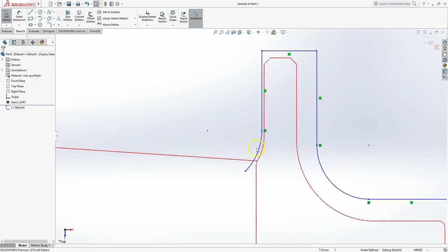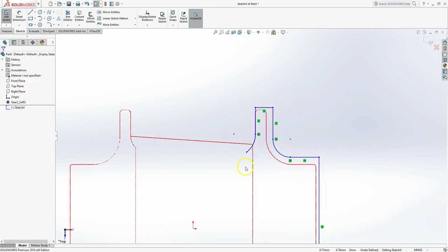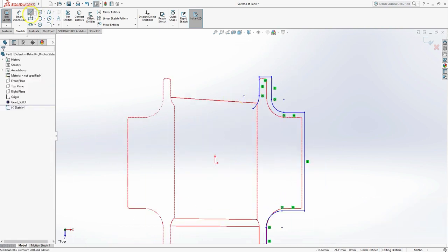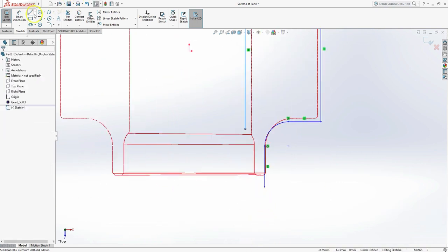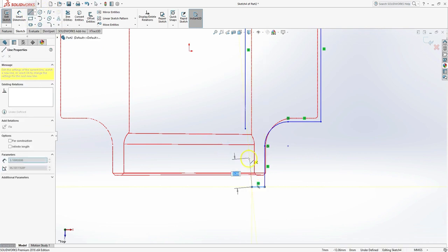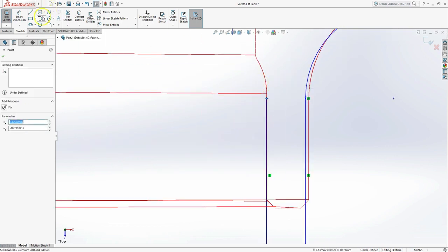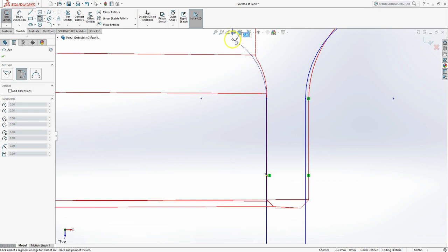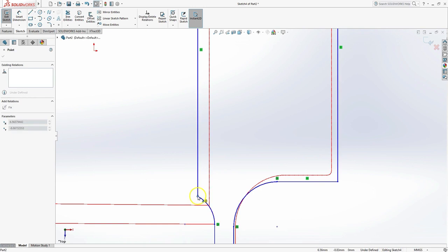Now, I'm going to do something a little unique. On the inside here, I'm actually going to make sure I have extra material because we're going to be cutting that out later. So right here, let's see where I'm working. Go ahead and make sure I have extra material in this surface here, actually skipping away from the line, and get that last set of curves on the bottom. Okay, and a tangent arc oversized to there, just like that, and make sure those guys connect there.